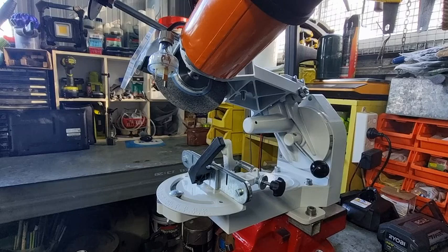And if you get some hook in that situation, you'll find it's much more susceptible to getting damaged, and if it's too pointy, it can get blunt much quicker. So yeah, try to avoid too much hook on a full chisel. You've got no problem on a semi chisel. You don't have that problem. It's only full chisel.